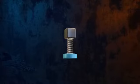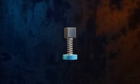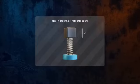But first, we have to make a few assumptions. We'll assume that the mass can only move up and down. Since the system behavior is defined by a single output, the x-coordinate of the mass, this is what's called a single degree of freedom model. We'll also neglect the effects of gravity, and for now, we'll assume that there's no damping, meaning that no energy is lost from the system as it vibrates by friction or other means. No external loads are acting on the system.